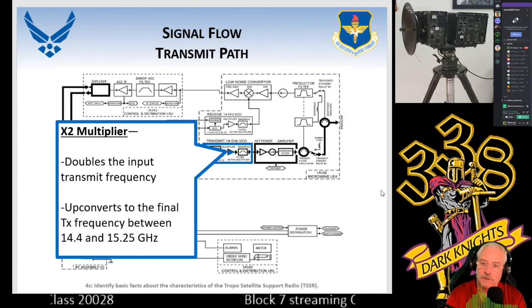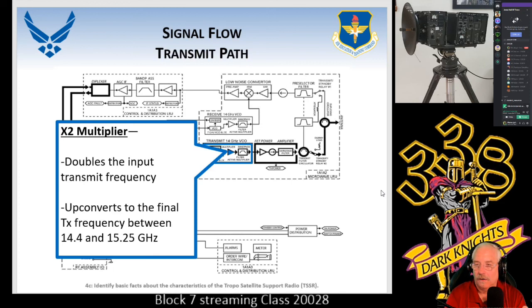Harmonics being a multiple of the frequency. With this in mind, your first harmonic is going to be between whatever you dialed in, which is a 7.2 to 7.625. The second harmonic is actually going to be the 14.4 and the 15.25, and then the third harmonic, the fourth harmonic, and the fifth harmonic.